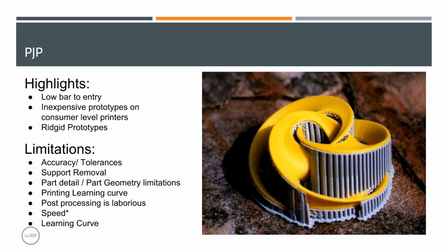The support material, right? So there are materials that are soluble. It's not what I had anticipated initially as soluble. It does take a while for this material to actually dissolve. So yeah, you do need a bath overnight typically. And if it's not soluble supports, it's breakaway, which can damage the part significantly and or be very laborious. It takes a while to break away that support. It's kind of rigid.